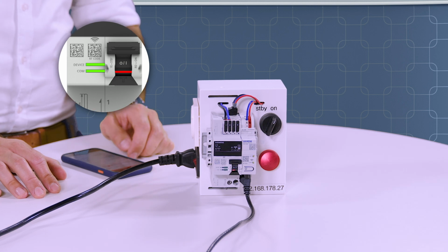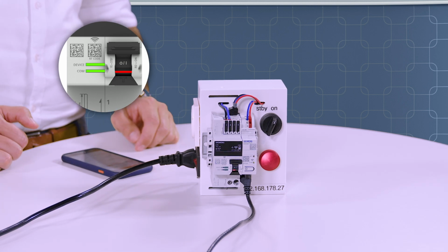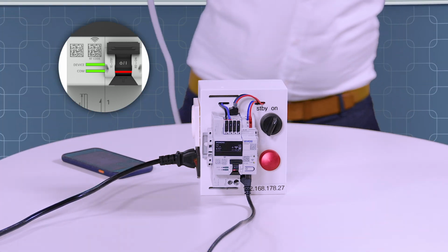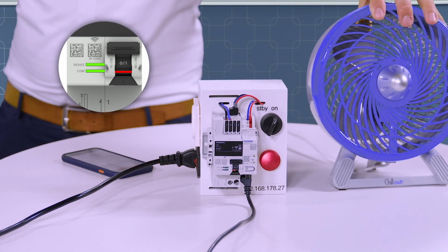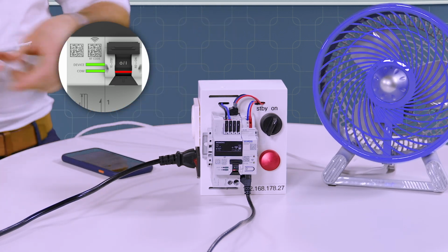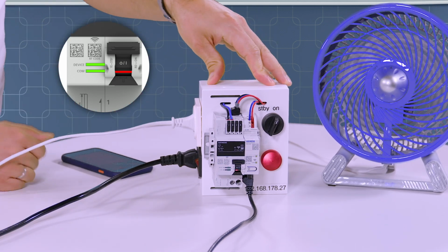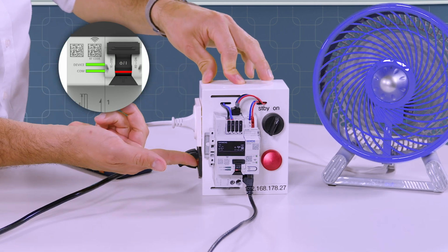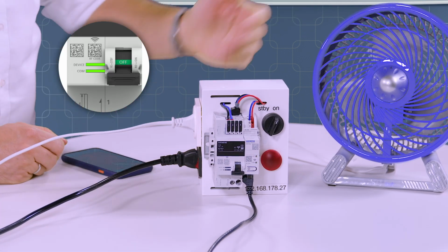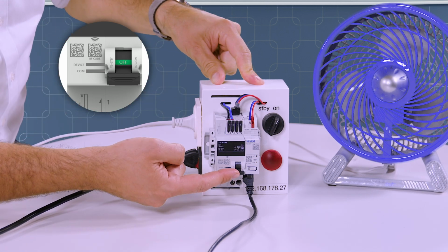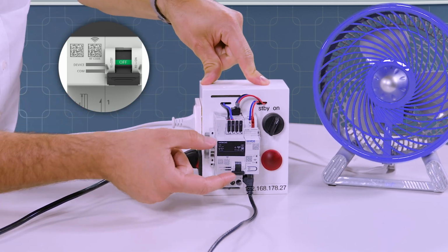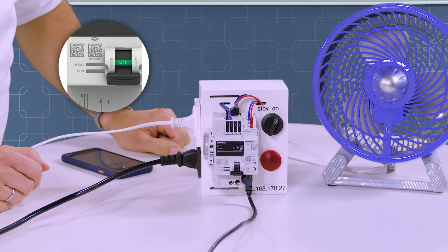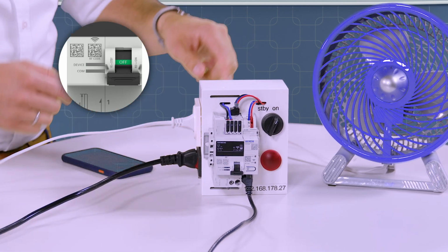So what we now want to show you is, for example, if we really have an undervoltage. So let's take again our load. We have here the setting of our fan. The fan is working, and when we have an undervoltage, for example, we have here the power supply off, the fan is off, and you see the device is also off. And if it's really off, you're not able to reclose it. So it's really locked to an off state.